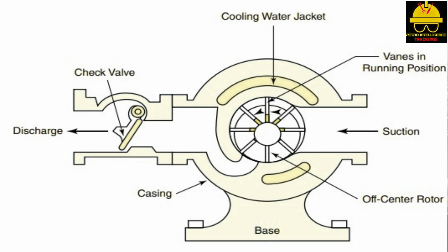Sliding vane compressors require lubrication between the vane and contact surface. Lubricating oil is injected into the suction side of the compressor. This procedure helps prevent internal slip and provides a positive seal. Sliding vane compressors are typically non-pulsing systems.